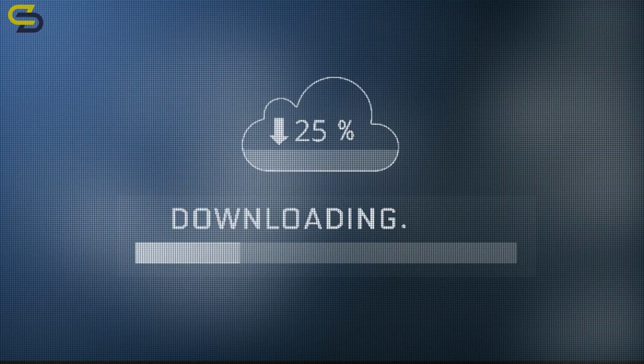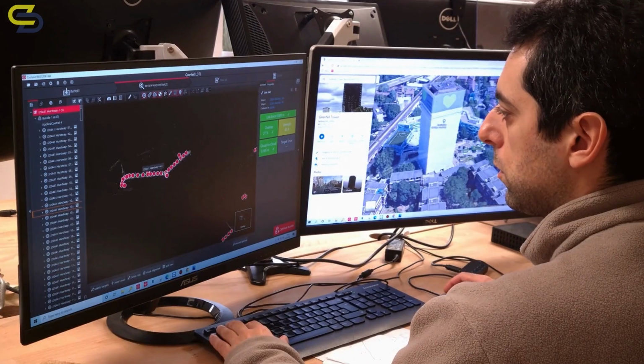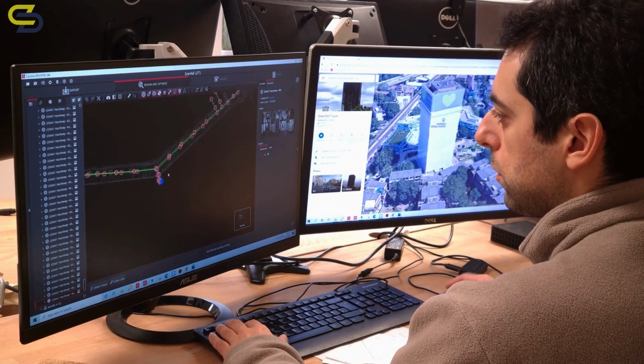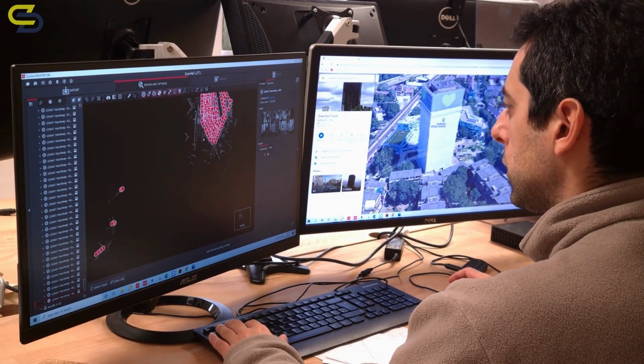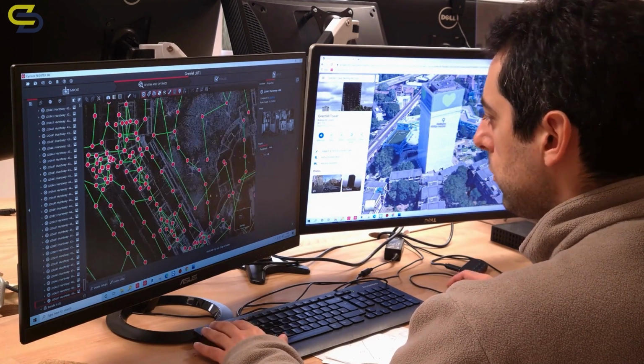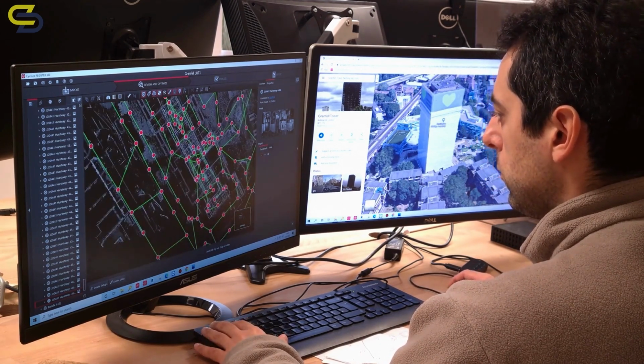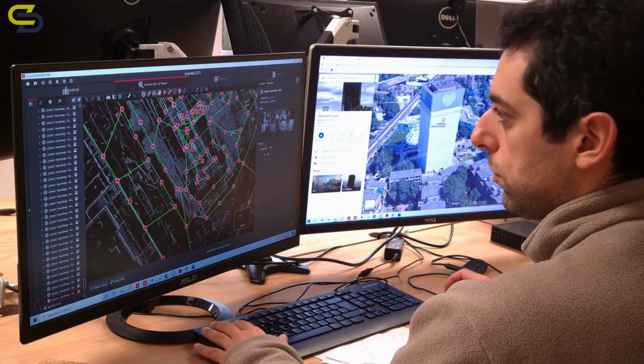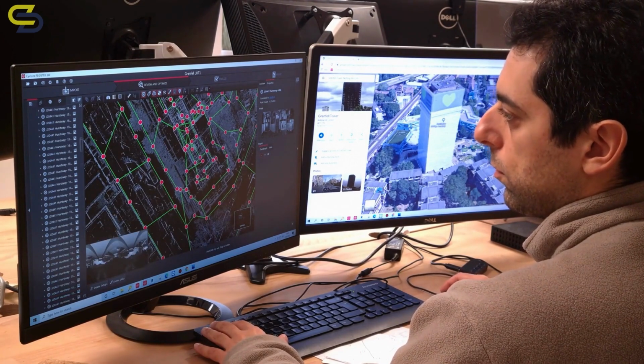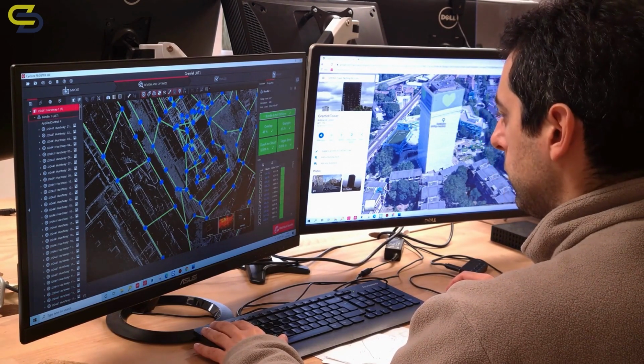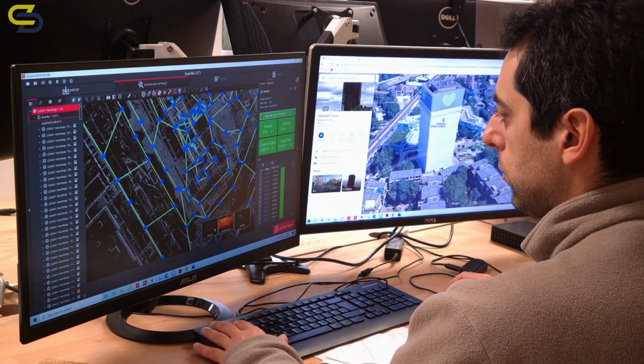Alternatively, your surveyor should be able to supply you with a downloadable file that can be stored on your own infrastructure and then imported into specialist software. There are many different file types: E57, LAS, PTS, OBJ and RCP are just some of the common file types. So always check with your surveyor before starting your project.